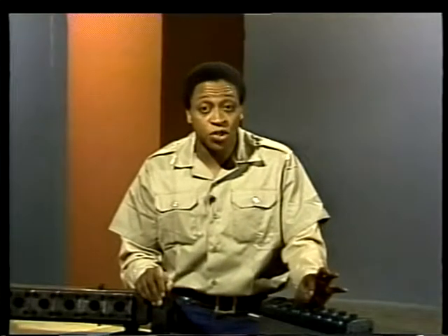If the gaskets stick and can't be removed easily, sometimes a special tool supplied by the gauge manufacturer can be used to get them out without damaging the seating surface. When no special tool is available, a brass scraper or brass wire brush can be used. Do not use a steel tool because such a tool is very likely to damage the seating surface.